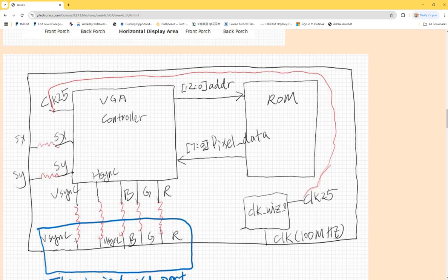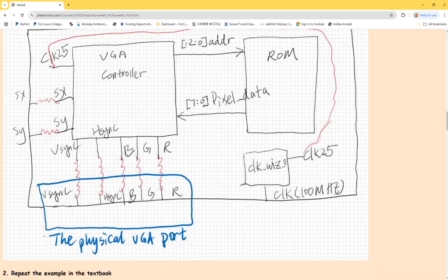It's ready. So if you design a VGA controller, you are throwing the address to it, and you can expect 8-bit data is available for your VGA controller. You can directly take it in, right? You take it in, and then do something. You can look at the Verilog code, what we did over there, and directly assign it to all these VGA ports. So that's the interesting part of this technology.